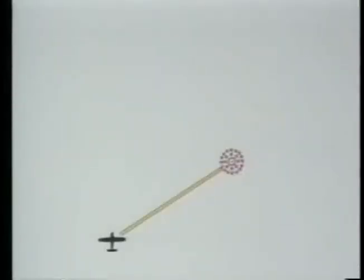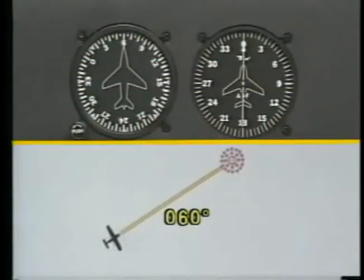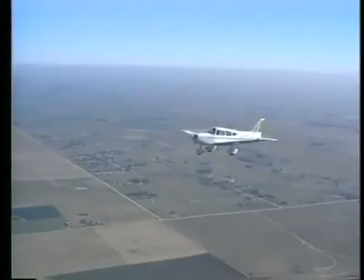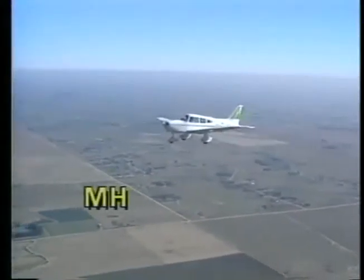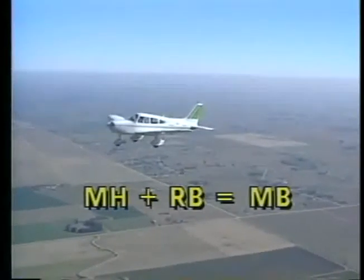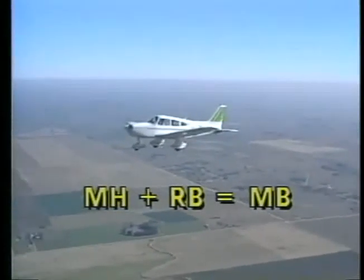If your airplane is on a magnetic heading of north, you simply need to turn to a heading of 060 degrees to fly to the station. At the completion of the turn, the ADF will be pointing toward 0, indicating the station is directly ahead. If you're flying a magnetic heading other than north, you must add your magnetic heading to the relative bearing to find the magnetic bearing which will take you to the station.